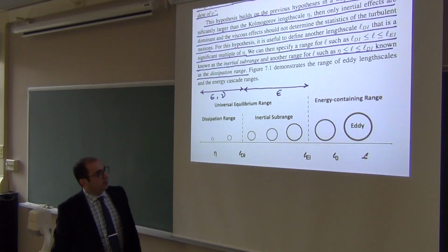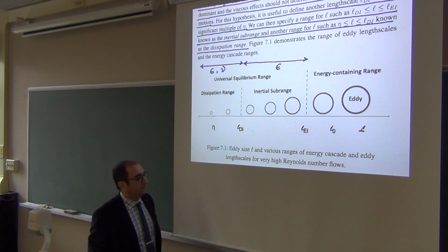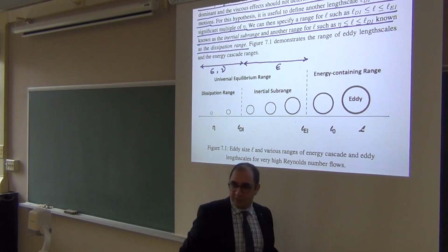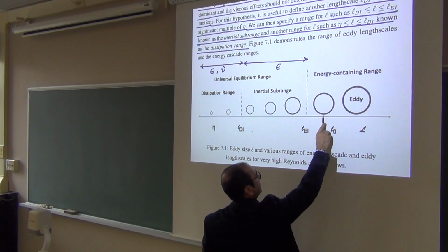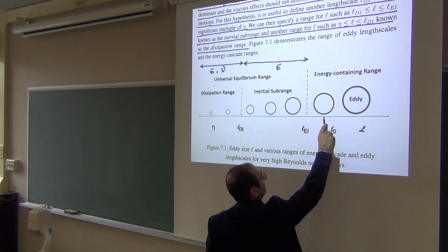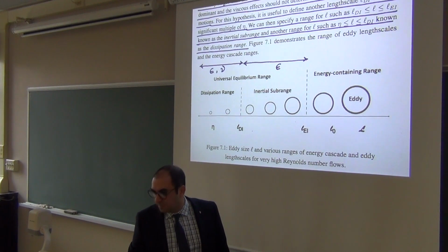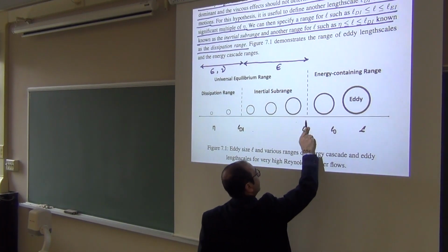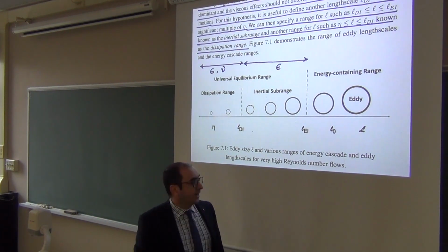It's all about scales, right? For a flow, let me put it this way. Let's say the building is 50 meters, the size of this building. The largest eddies formed around this building are on the order of 50 meters, maybe 40 meters, maybe 45 meters, maybe 60 meters. It's the same range. The cutoff range there may be, for the building, 20 meters, right?